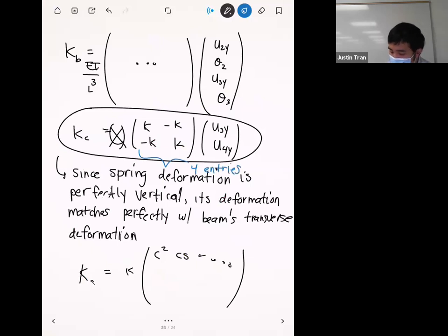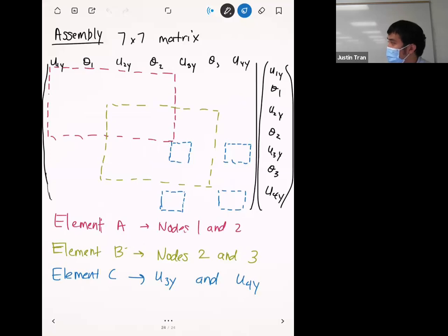And so there should be 4 entries in the assembly where this is applied. And you can see we have 1, 2, 3, 4. Okay. And so we're good to go. Because when you're doing disjointed element stiffness matrices like that, it can be easy to lose track of a term or highlight one term or one section more than the other. And so the easiest way is just to count it up and make sure that you have the right number there. Okay. All right.